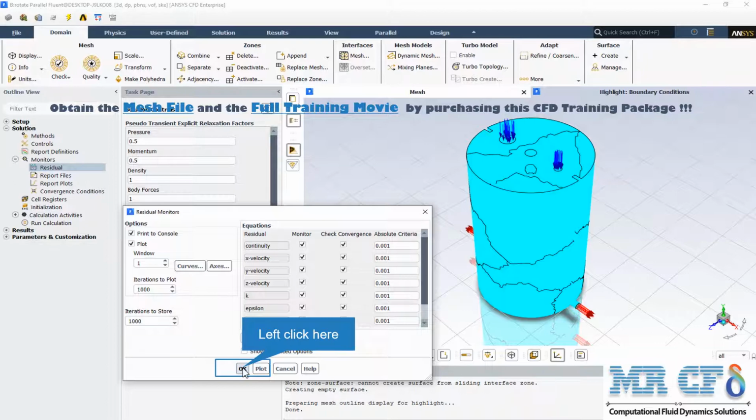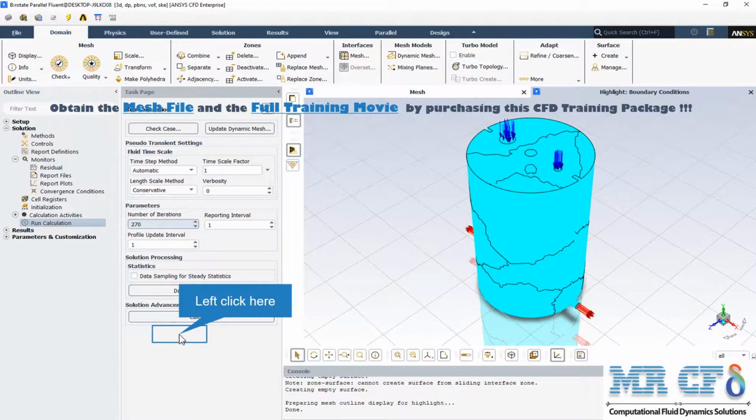And finally, the absolute criteria or relative criteria shows the residual value for which the solution of each variable will be considered to be converged. To set this value, manually enter the new value in the corresponding absolute criteria field. And that's it. Set the number of iterations, here it is 270, and just click on the Calculate button to start the solution.